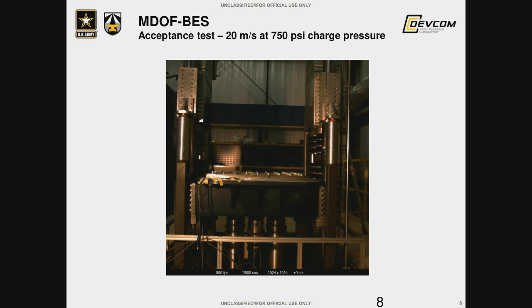What we would see here is the bullet mass rising upward, striking the underside of the test platform. The test platform would move through some distance of several inches before it contacts the elastic programmers on the underside of the arrestor mass. These programmers are adjusted to produce the pulse durations needed for any given experiment.